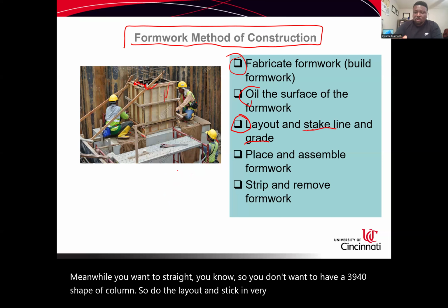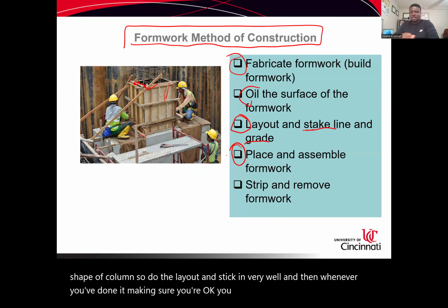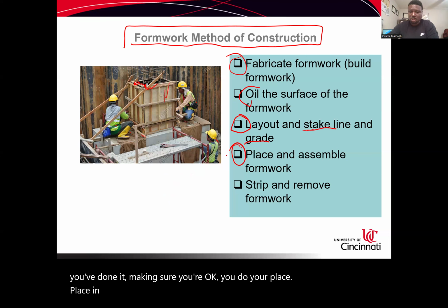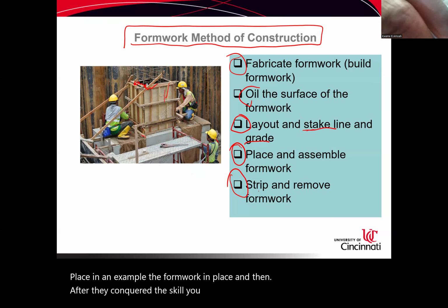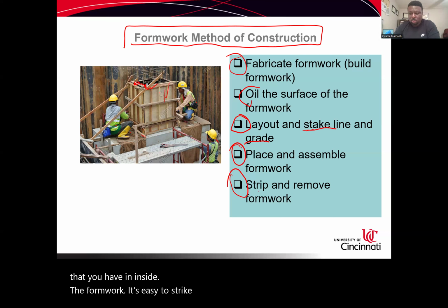And then whenever you're done, making sure you're okay, you do your placing and assemble the formwork in place. And then after the concrete is cured, you strip and remove it. Based on the oiled surfaces that you have inside the formwork, it's easy to strike it, possibly reuse it somewhere else in the project.